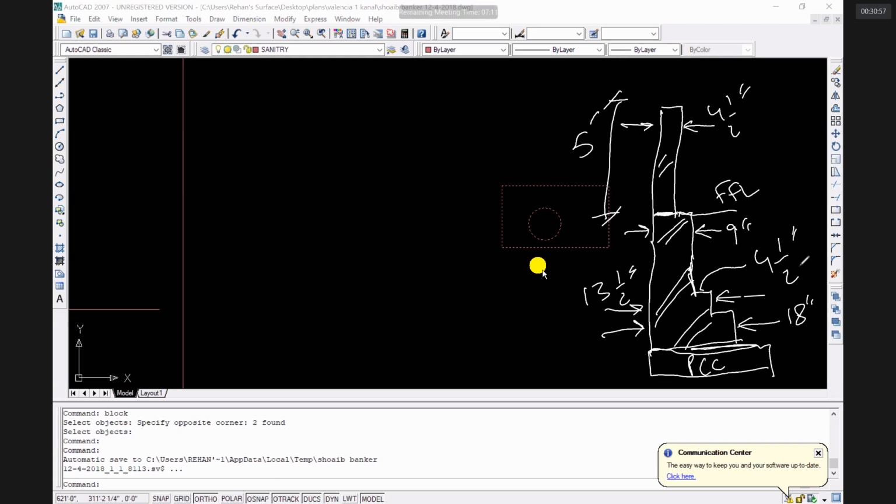Good. Mohammed Sham is asking, if the slab shade has to be kept outside, which line will we show it with, dotted line or dash line? Ehtisham, it is a dashed line. Any shade projection which is above the lintel height is shown with a dashed line.